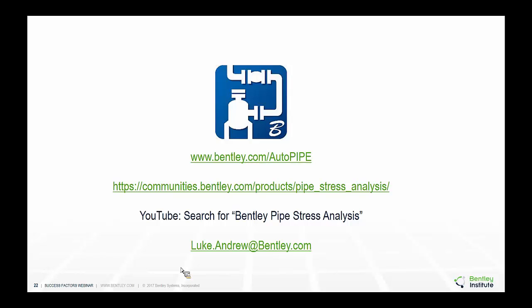Correct. And continuing with the question, the second part is, can the stress analyst modify these supports after that? There won't be any modifications in STAAD, but AutoPIPE can modify those supports as needed. If the steel needs to be more or less, or the steel can't handle that type of support, then you can modify your model, and then you can keep sending it back and forth between the two designers.